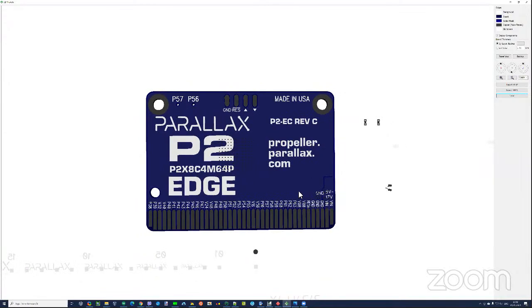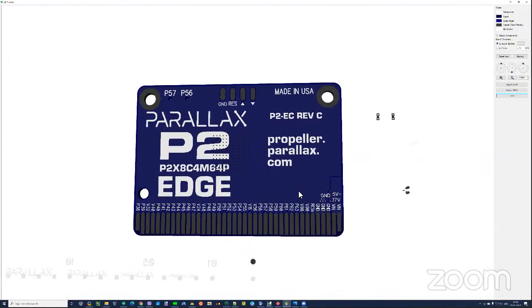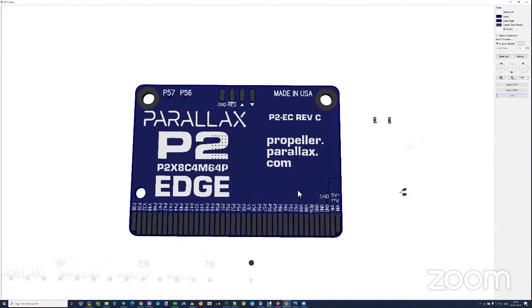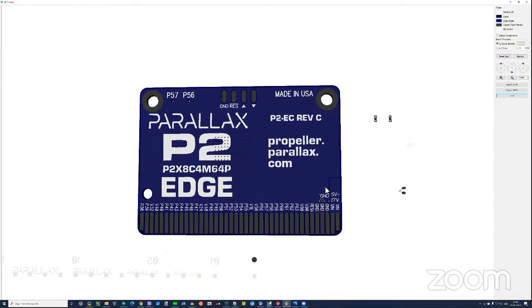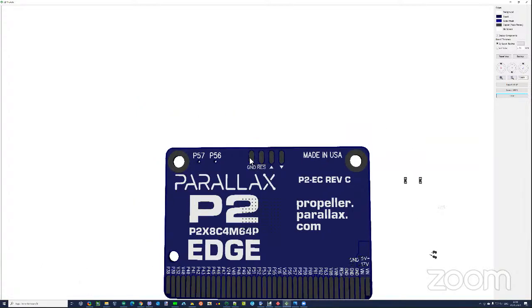But all things considered, it became quite awkward having them there. So we've dropped the separate 5-volt and ground inputs on the basis that if someone really wants to solder a right angle connector onto supply power there, they could just drop one over these edge connectors anyway, because the pitch happens to be right for that.